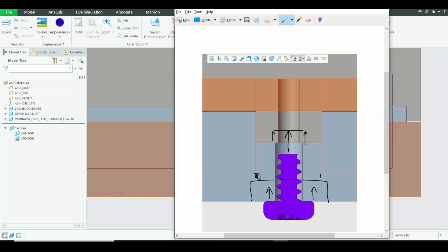Now when I'm enlarging the hole at this region, you can see the thickness of this surface will be extremely low, so we shouldn't have non-uniform thicknesses in the model. Therefore, we need to add certain material like this. Adding this material will create a smooth surface in this fashion, so the final material will be shaped like this. Let me change the color.